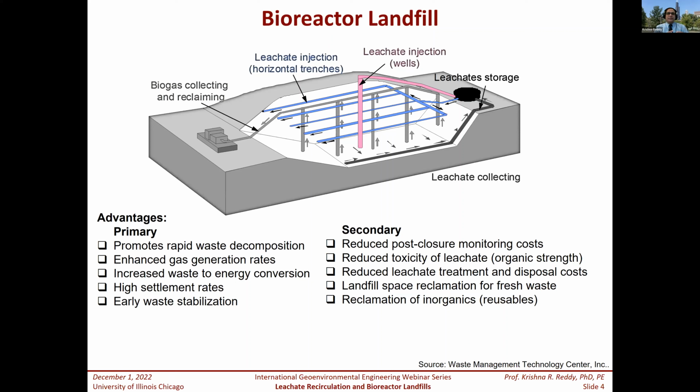The idea is to be able to distribute the leachate uniformly across the waste. The idea is to increase the moisture content and create conditions that are conducive for enhanced biodegradation. So remember, before we had a low moisture content, that's the problem. So now we are increasing the moisture content through this recirculation.